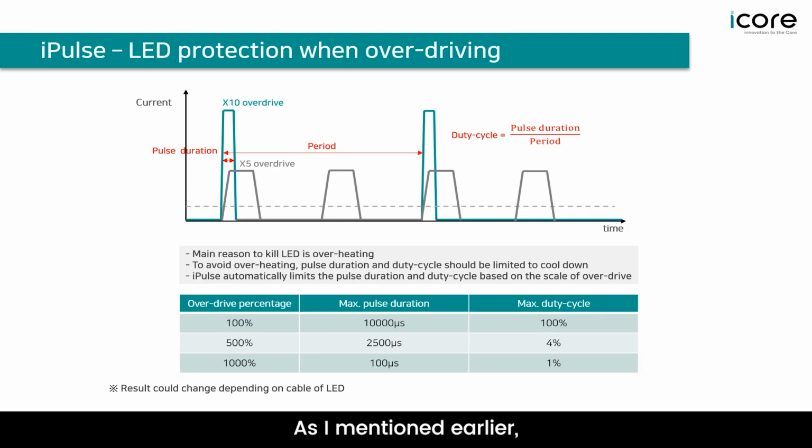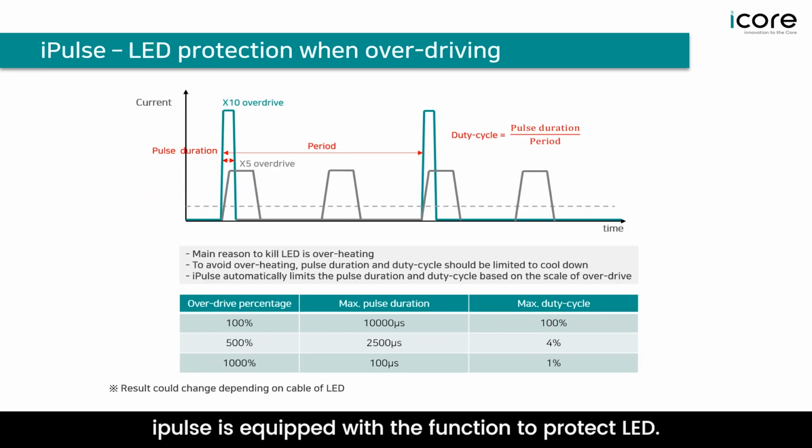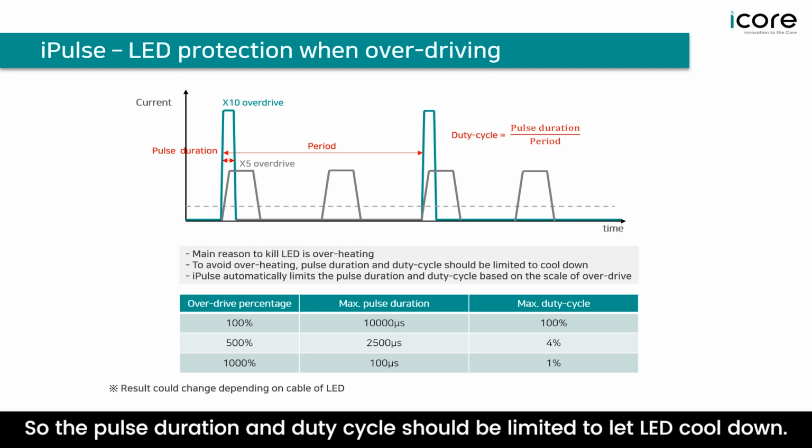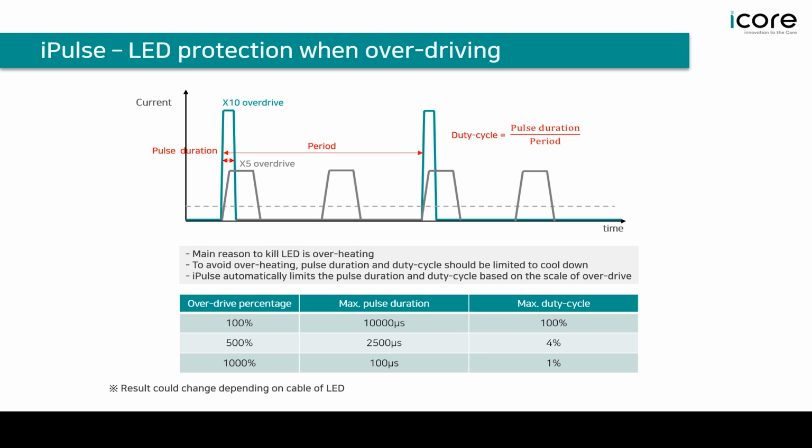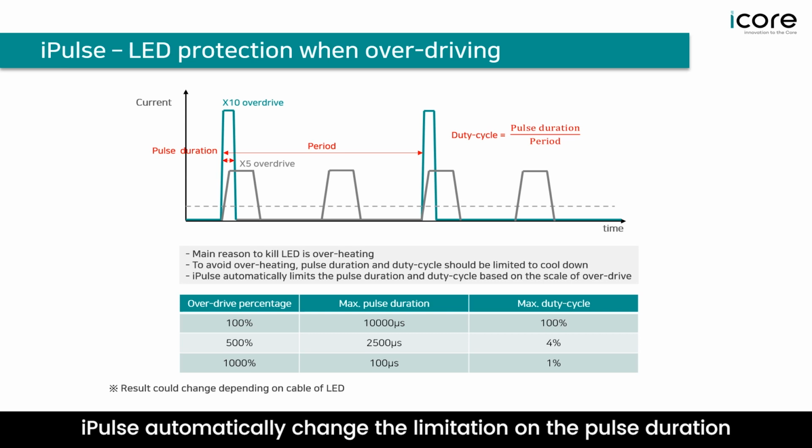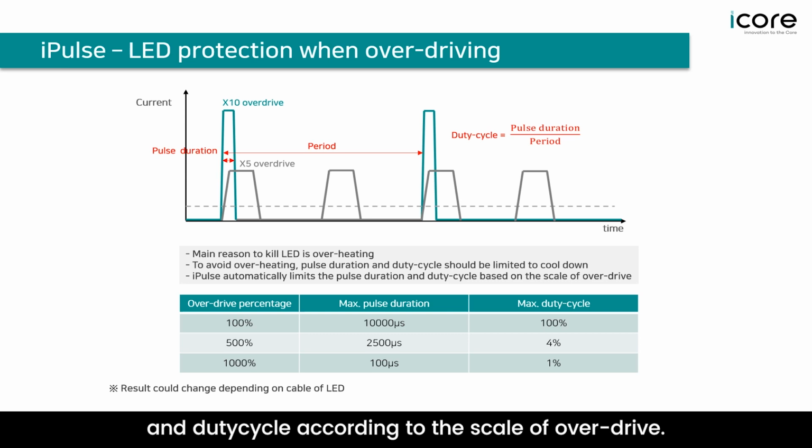As I mentioned earlier, iPulse is equipped with a function to protect LED. When overdriving, LED is put at risk of overheating, so the pulse duration and duty cycle should be limited to let LED cool down. iPulse automatically changes the limitation on the pulse duration and duty cycle according to the scale of overdrive.